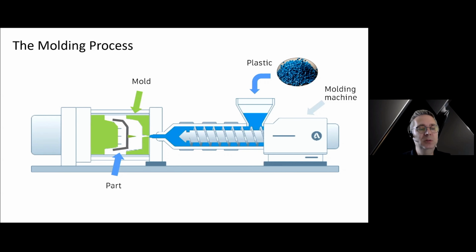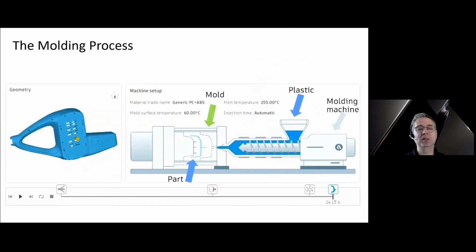So once they are melted, we're going to then inject them into the mold. And then as the part solidifies, and I mentioned that they expand slightly while melting, they shrink slightly as you freeze them. But once they are in a solid state, the part is then ejected, and we basically repeat that for as many parts as you need.